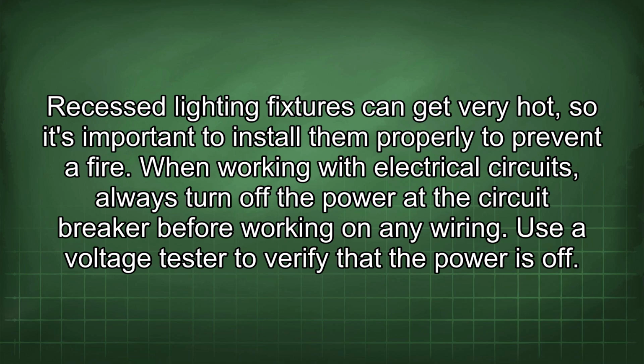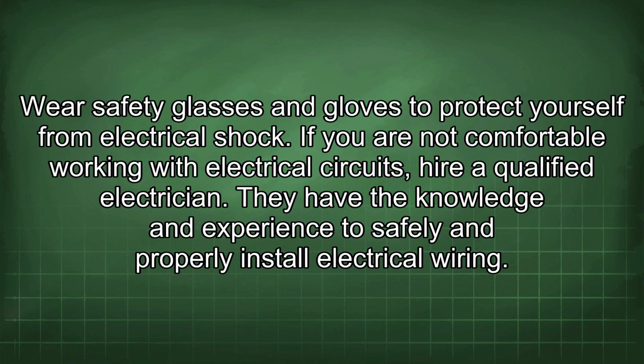When working with electrical circuits, always turn off the power at the circuit breaker before working on any wiring. Use a voltage tester to verify that the power is off. Wear safety glasses and gloves to protect yourself from electrical shock. If you are not comfortable working with electrical circuits, hire a qualified electrician.